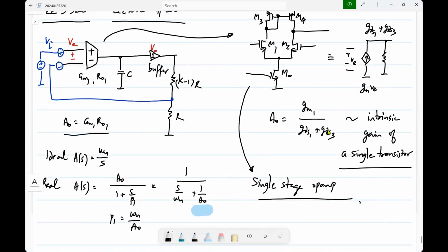So that is, it depends on the context. Maybe there is a load that you have to drive. And if there is nothing, it is basically the parasitic capacitance of the transconductor itself and whatever else is following it. So it depends on where it is being used. So in some cases, you may have to drive a capacitive load explicitly. But anyway, whatever load means, whatever comes next.